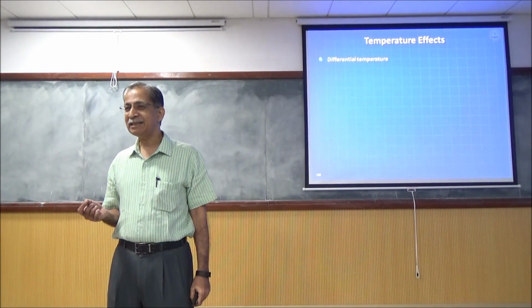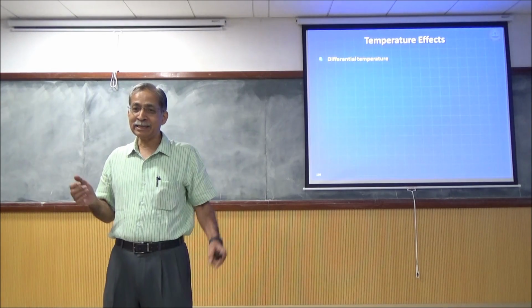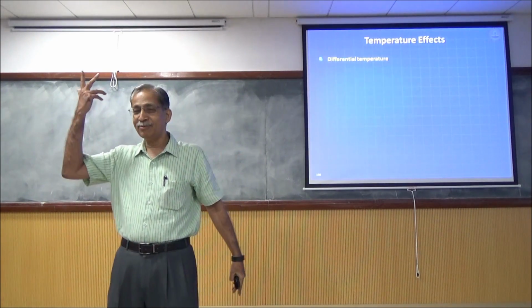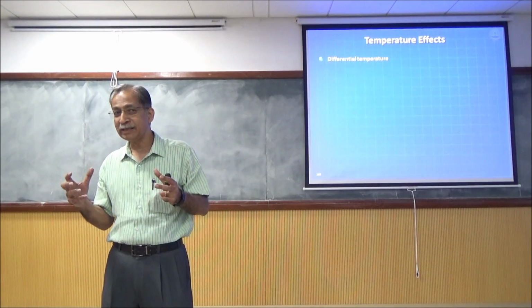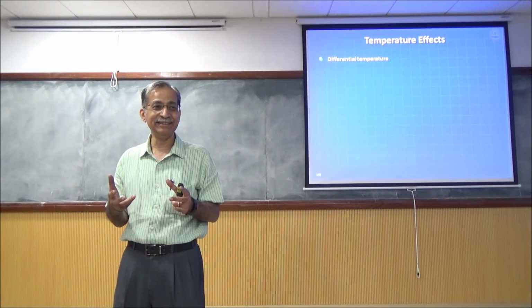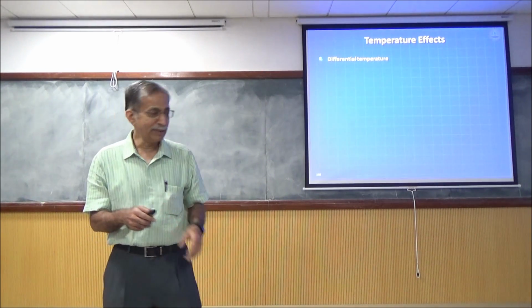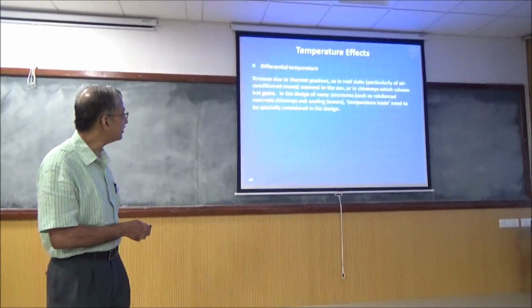So it's actually a little funny that engineers stop the building at 45 meters and think that I don't have to worry. Of course you have to worry. The challenge is that once a concrete cracks, its stiffness degrades. And so the tension will come. So it's a deformation-induced tension. Can I spill over for a few minutes? I want to finish this now.